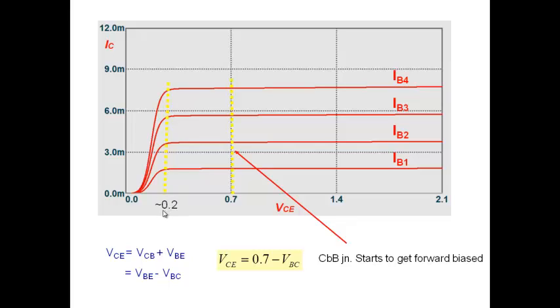Again, note IC by beta IB is less than 1 in the saturation region. If you are in this region, IC will be equal to beta times IB4. As you go into this region here, note the collector current is decreasing and the base current is constant. In this case, one is maintaining that by applying a current source to the base. So the base current is being kept constant, and the collector current is increasingly dropping, and therefore IC by beta IB is less than 1.